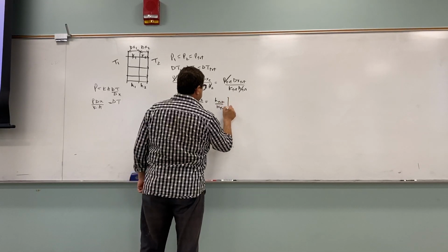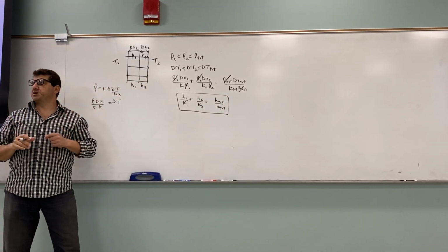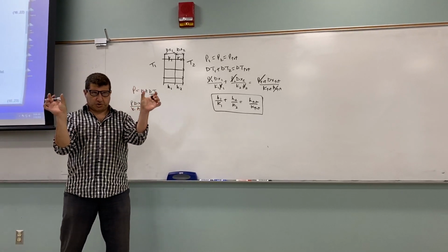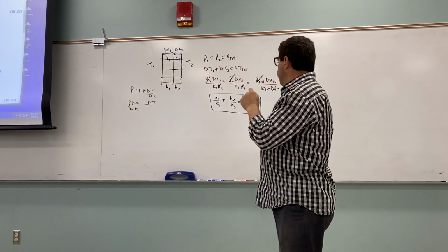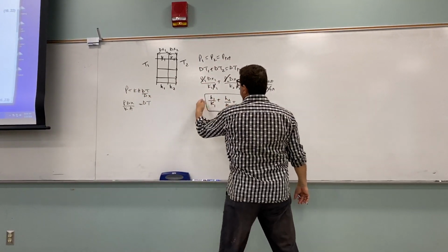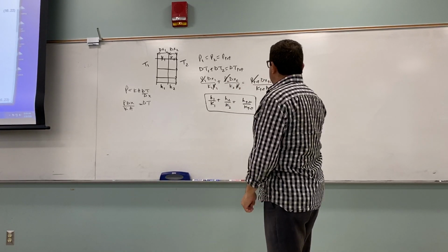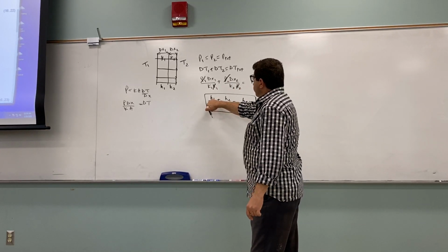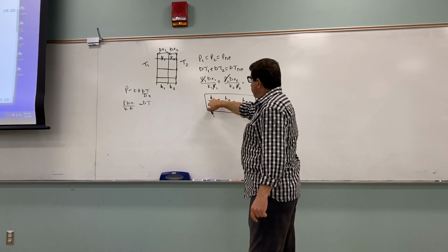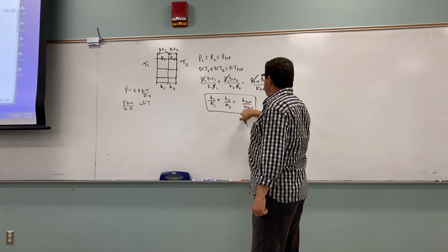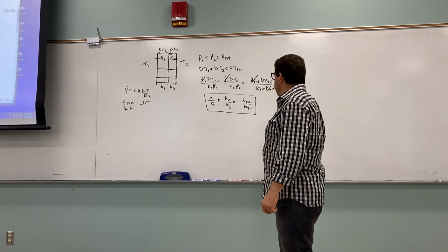And then we did an example of that for a house that had 3 layers. The wall had 3 layers, 2 dry walls and a fiberglass. And then we added, so if you have 3 in series, you can just add easily like that. So remember that the top one could be in centimeters or meters because the units of that cancel. And then the units of the K total comes out the same as the units of the K1, K2, okay?